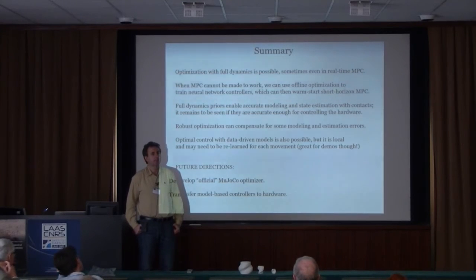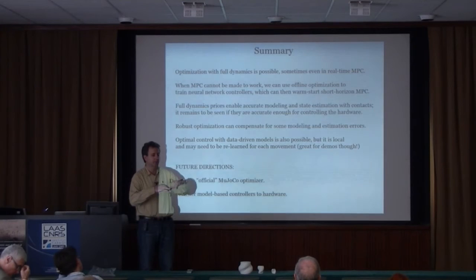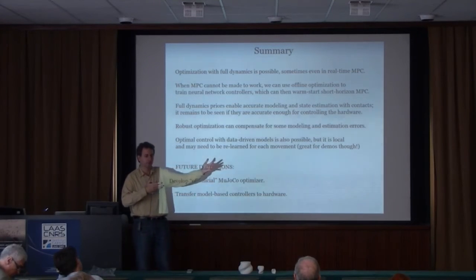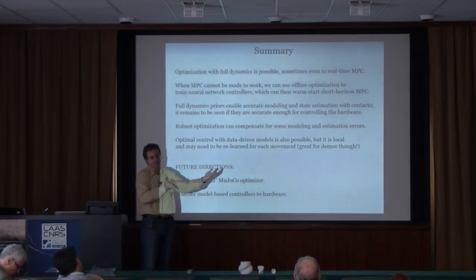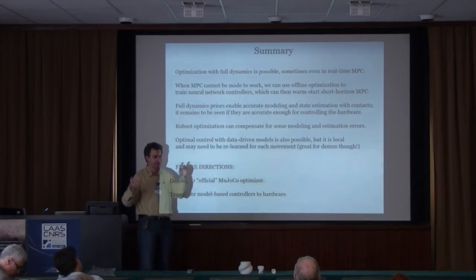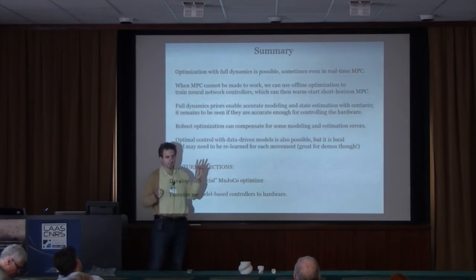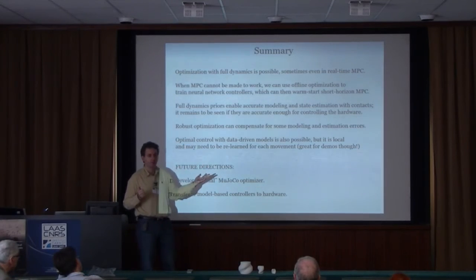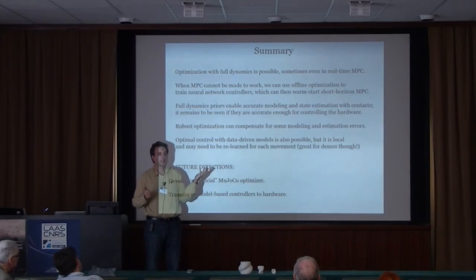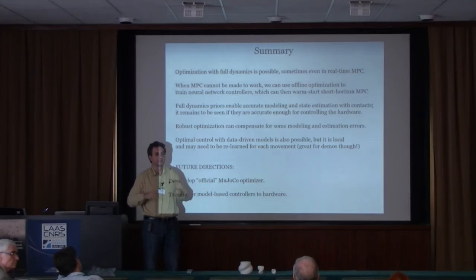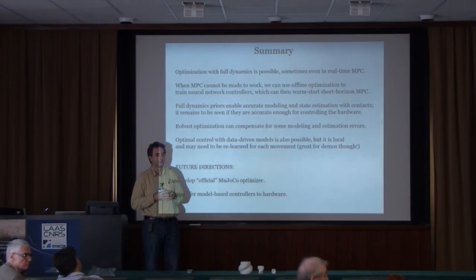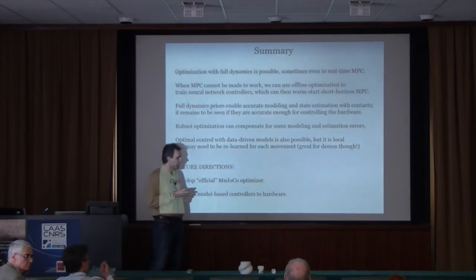Control horizon versus sampling, that's an interesting question, and in fact you could consider non-uniform sampling, where in the future you sample more sparsely, and we haven't actually done that, but it's probably a good idea. But this is a computational limit. You kind of figure out what it is given the computer and the system. The cost function, like I said, it takes tweaking, which is why we developed a tweaking language. In practice, the guys in my lab can usually get a new task running in 2 days with trying a few things. And very specifically, do you put anything inside for ensuring stability, like a terminal constraint or similar?